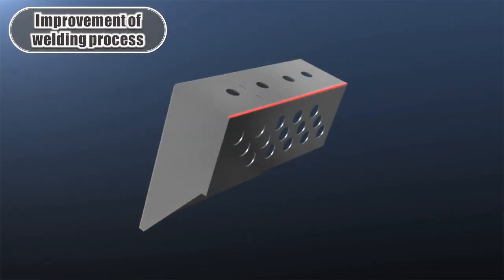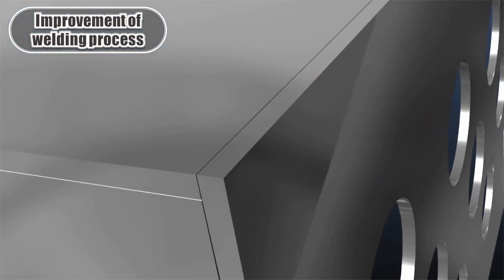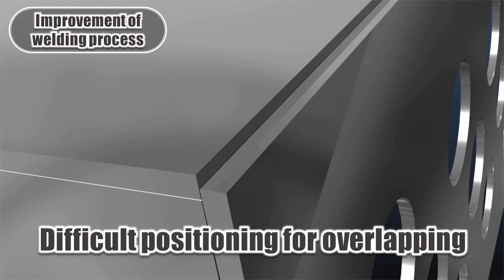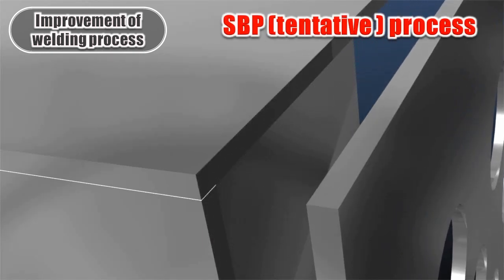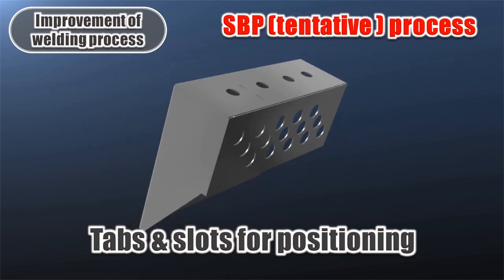When our shape is being welded, the sufficient 50-50 weld overlap is necessary, which is very difficult with positioning tool overlapping. We would like to introduce you an effective way to position the welding overlap: the addition of tabs and slots that are half of the sheet thickness.